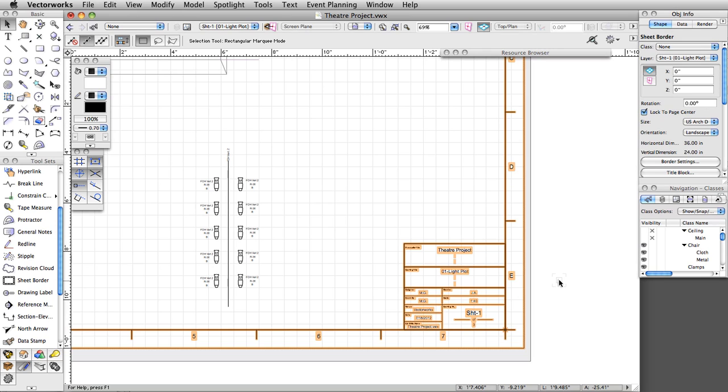You can place a schedule directly on the sheet layer, or you can create a viewport of the schedules we placed earlier on the paperwork design layer. Creating a viewport of a schedule will give you easier control of the size of the schedule. You will be able to adjust the scale of the schedule in the same way as we adjusted the scale of the light plot viewport. We will show placing cropped viewports of the schedules.